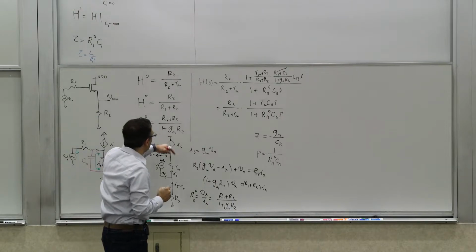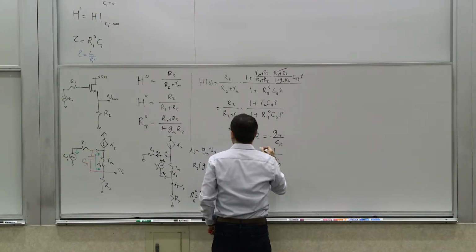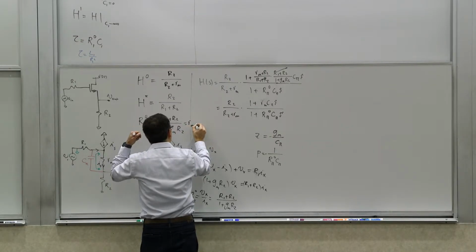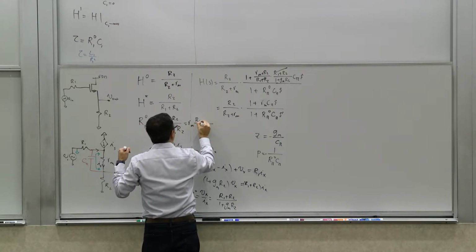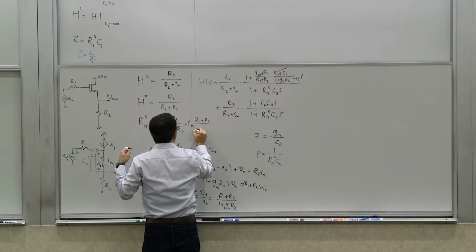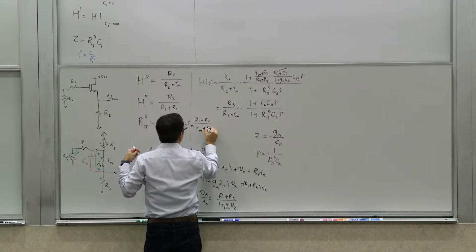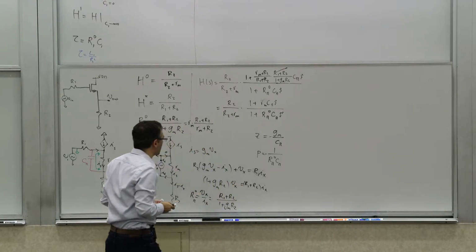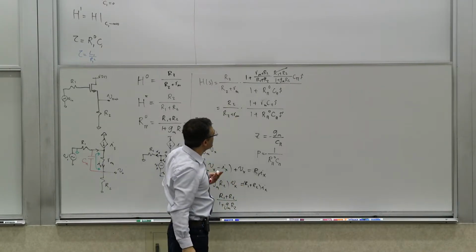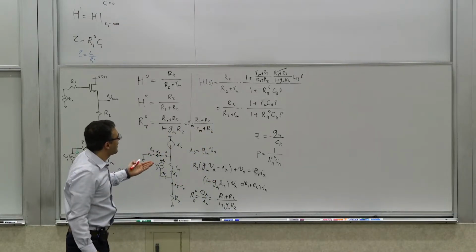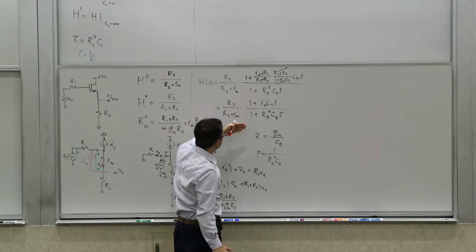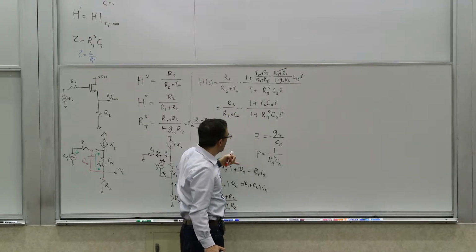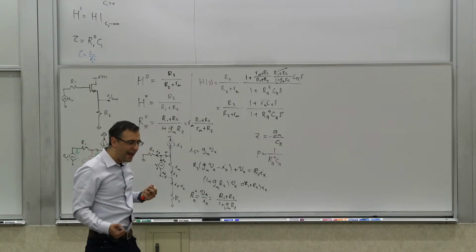And if you look at that, you can also rewrite this, so if you look at R pi 0, you can do the same thing here. You can write it as Rm times R1 plus R2 divided by Rm plus R2, if you want to write it that way. And you can use either one of the forms. That's fine. So the key point from this discussion is that you are getting a pole and a 0, both left half plane.